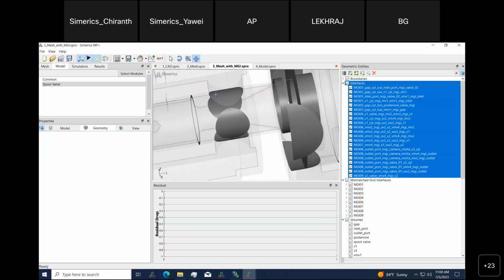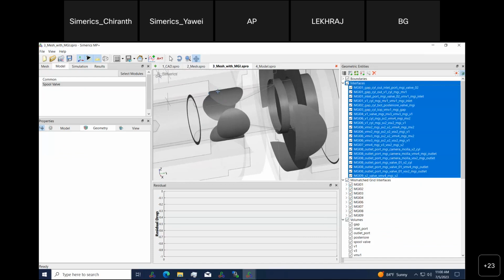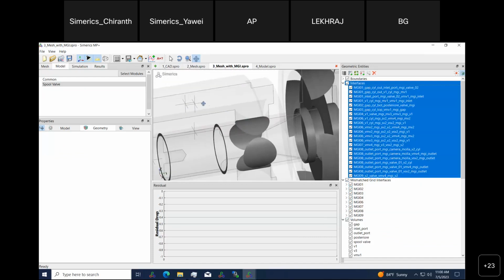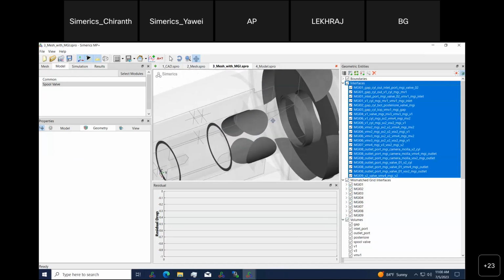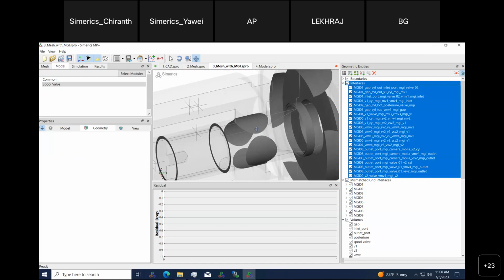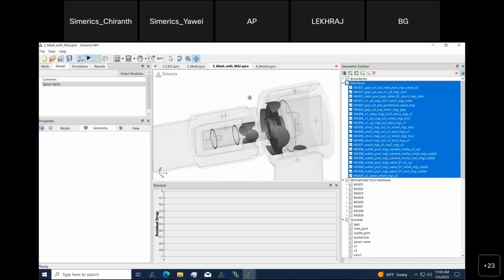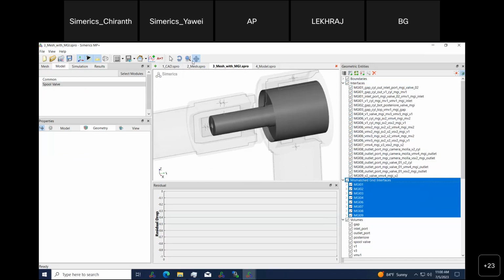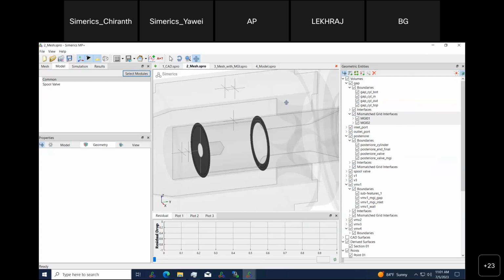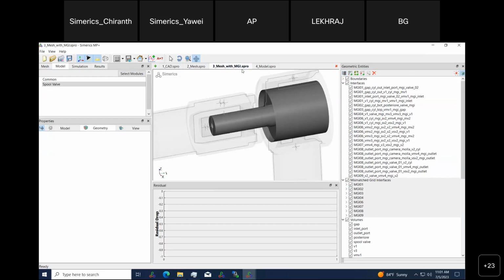You can see this one: the fluid comes from this inlet, and then it enters the valve domain through those 4 opening holes. And for those different MGIs, we have a total of 8. Basically, we just follow the same procedure to build up those different MGIs. So once we have these MGIs, we connect different volumes. Next step is to add the solver.